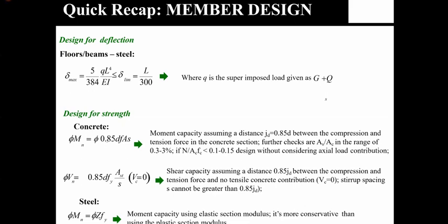So one thing to continue further, if you want to compute the flexural capacity of, say, a concrete section, it's a quite simple formula, which is area of steel times the lever arm. Which you represent as jd, which is most of the times 0.85d, right? And also you have to do further checks to make sure the steel to concrete ratio is in the range of 0.3 to 3%. And if your actual demand on those particular concrete elements is, say, less than 0.15%, you simply ignore its contribution. These are simple basic methodologies to compute the flexural capacity of your concrete section, right?